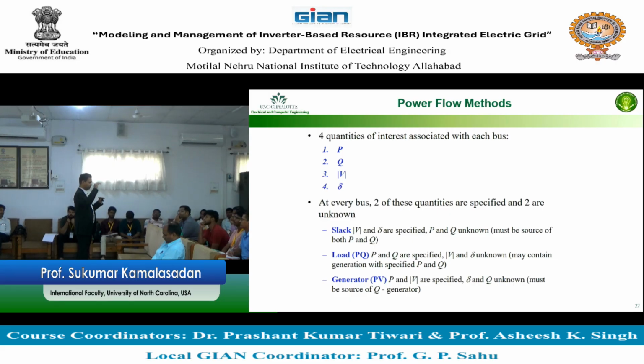Because of that wobble in speed, this box called the governor senses it and opens the valve for the generator, pushing more fuel to maintain the generator power equal to the load. This is done in 3 seconds. That's the response time of the governor. So the governor is one controller, and the excitation system is the other. What is the governor controlling? Power, voltage, frequency?